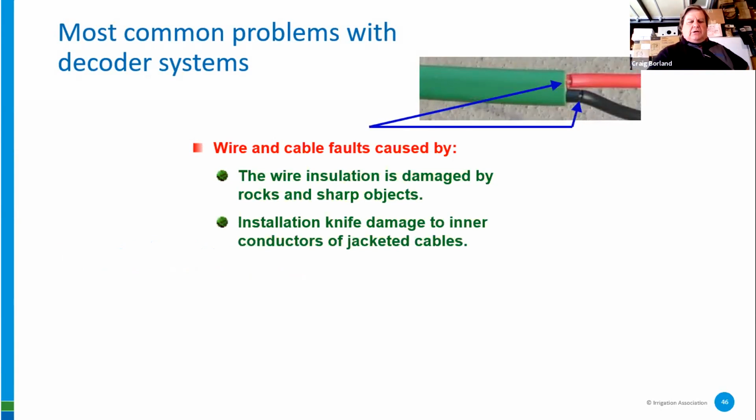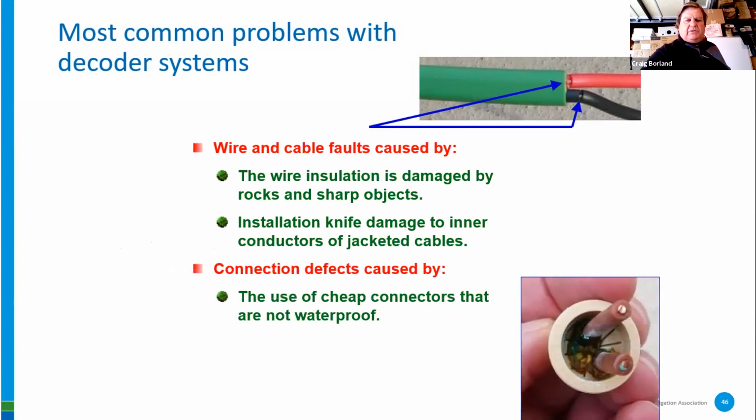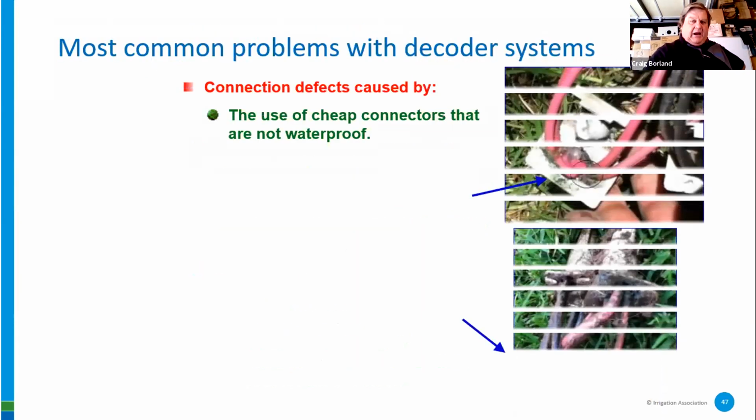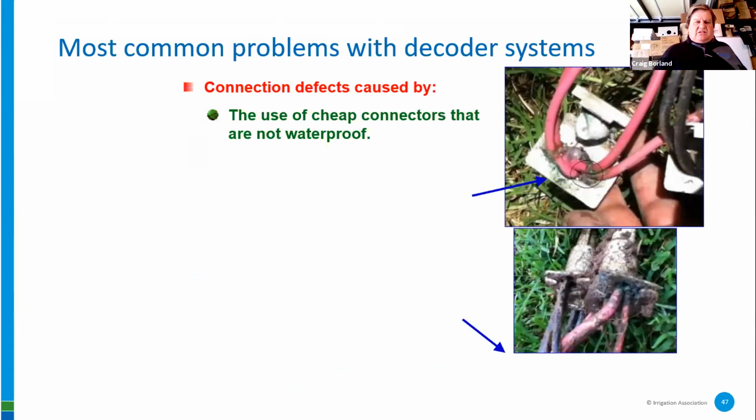is compromises on the wire insulation. Somebody cut the wire a little too heavy with the knife, or used the wrong style connector. If you look on the inside of that wire, there's green there. Well, that's oxidation occurring on the wire. With the wrong connector, the goo overheats and comes out of there, and it's no longer a waterproof connection. Using a proper connection is paramount to the system's longevity and working reliably.